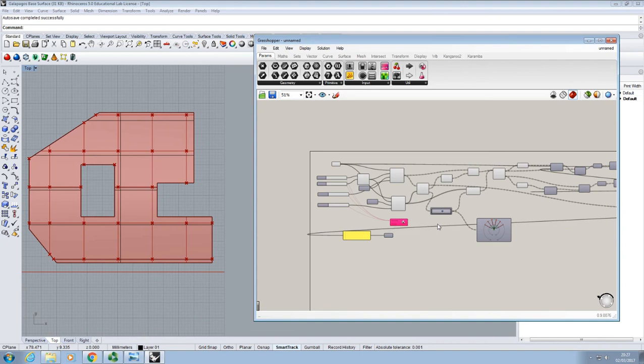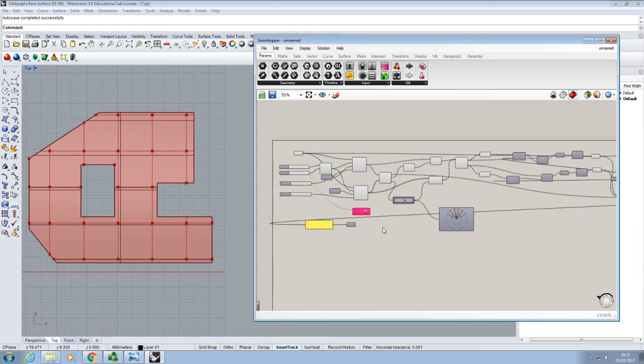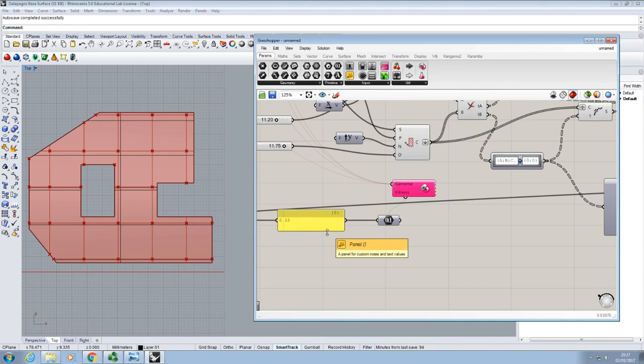What's nice about this is that you can essentially apply it to any type of problem you want. All you need to be able to do is express how good a particular option is as a score. In this case, what we're trying to do is minimize the number of columns, so our score is our number of columns. But in fact, this isn't really a very good fitness score for this, because it only varies in whole numbers. In order for Galapagos to work best, it needs to know whether one option is slightly better than another, or slightly worse, and so on.